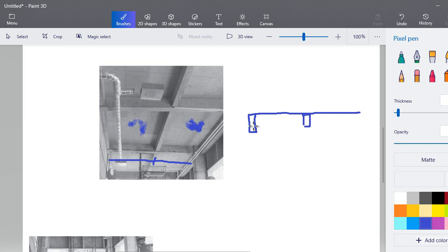Now the stiffness of this girder is more as compared to this slab system, so that's why the girder plays a fixed support right here. So that's why here we have a negative moment. We have a positive, then we have a negative moment. This is very important to understand. So here we have to use the coefficient, and here we have a positive moment, here a negative, here a negative.